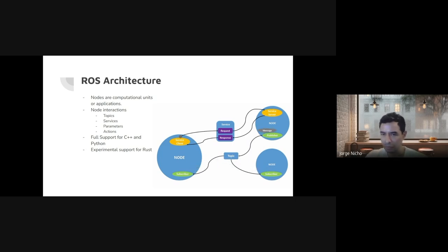The server will get the request, process it, finish it, and return a result confirming that the action was carried out as asked. Those are the two most common interactions that you can use in ROS. There are also actions, which are similar to services, but with a little more nuance in that you can monitor the progress of how the service request is being executed.